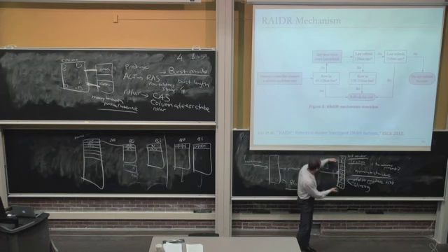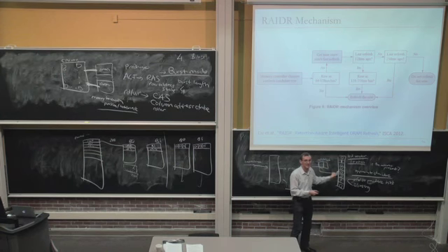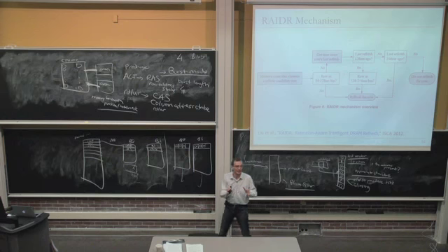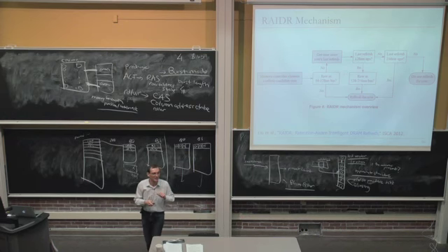Because your Bloom filter vector, let's say it has 1K entries and you use some bits to index, but as you have more rows to be refreshed, the number of bits that is set here increases. Right? So you'll still get correct operation, but you may not be able to save on refreshes.